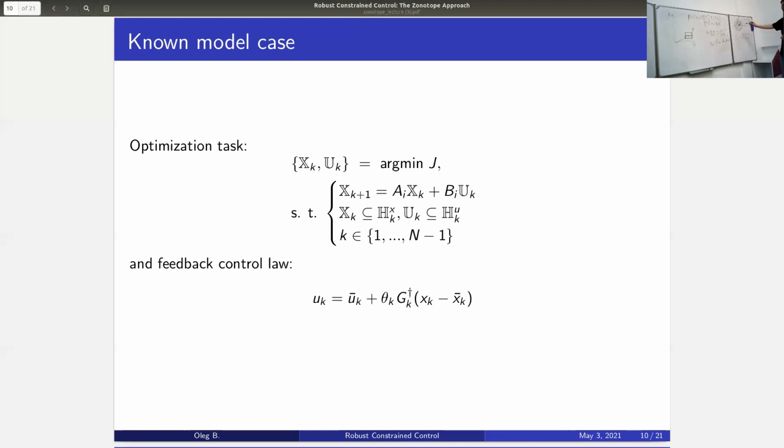But each point of our Zonotope is described as a linear combination of these two vectors. Any point we can project onto these two vectors, and after that speak about the behavior of these projections. It's the main idea of this concept: you can find feedforward control, and based on this feedforward control, find a policy for each point in this area.